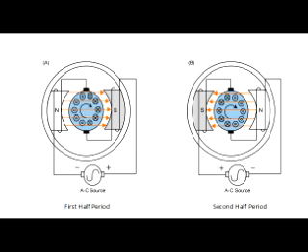This rotating flux induces voltages in the stator and rotor windings. If the rotor circuit is closed, current flows in the rotor winding and reacts with the rotating flux, and a torque is produced. In the steady state, the rotor rotates at a speed very close to synchronous speed.